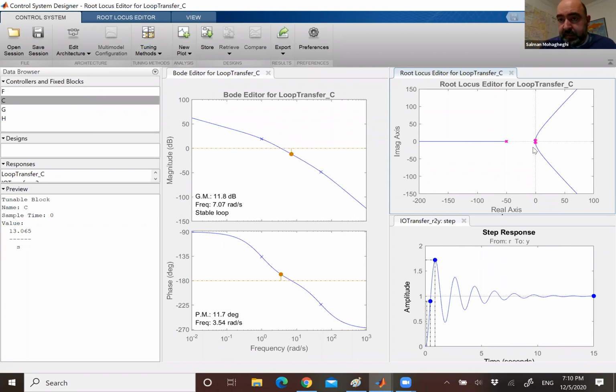With this system, it's always good to look at the response and see what you can say about it. If I look at the Bode plot, the magnitude is starting with a negative slope, which is great. That means that you have an integrator so you can track a unit step. Is this what I see here? Absolutely. Hover your mouse on this point and you see that the final value is 1. So perfect reference tracking for a unit step.